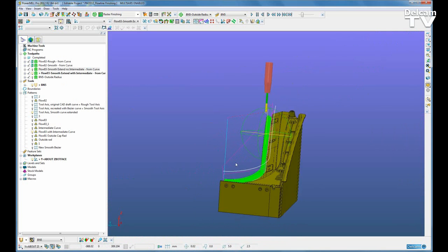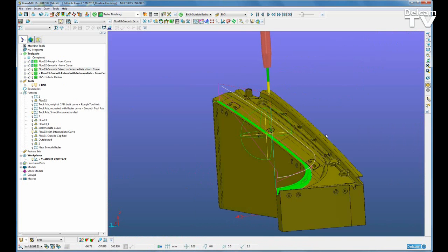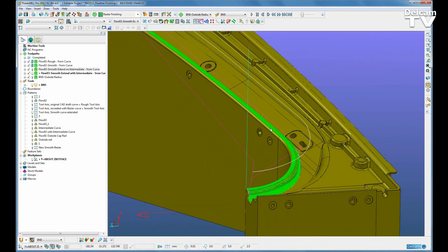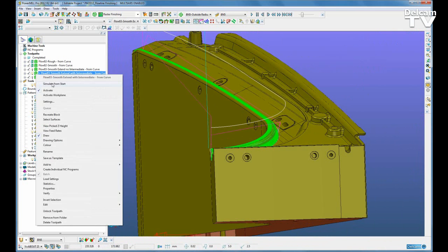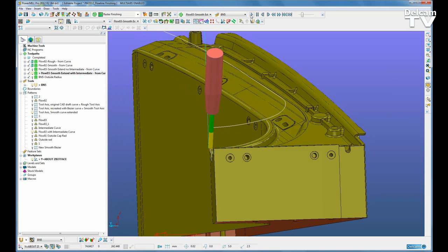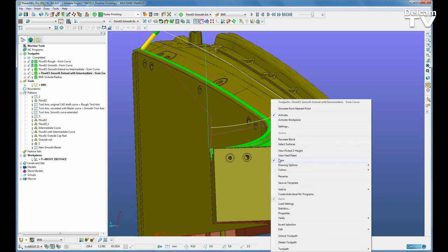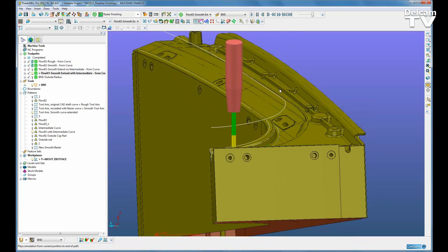There was a 5-axis flowline toolpath that's being created. We will now simulate this so we can see more easily. You'll see the tool starts on the first drive curve that sets the start of the first pass of the toolpath and progresses along the top face towards the end drive curve. Positioning the tool lower down, we can see now that smooth flow has continued throughout the toolpath.